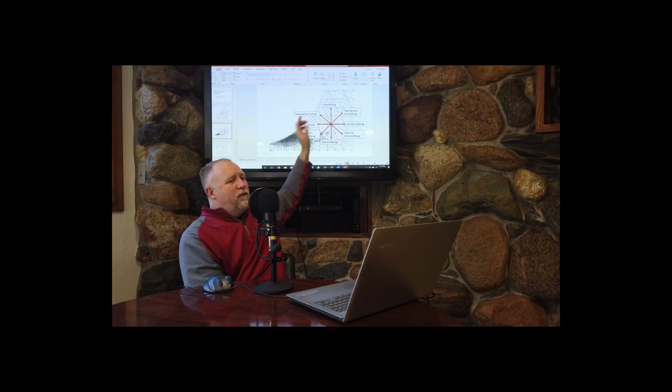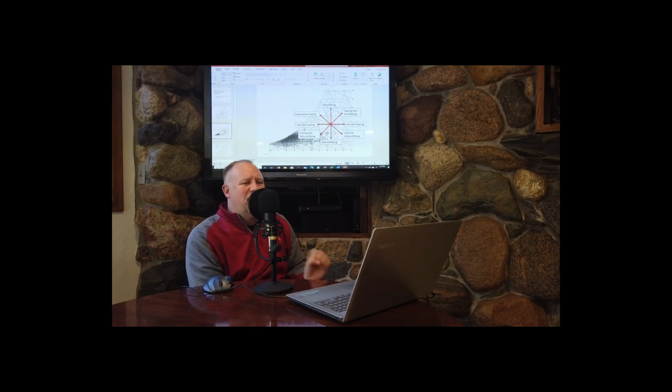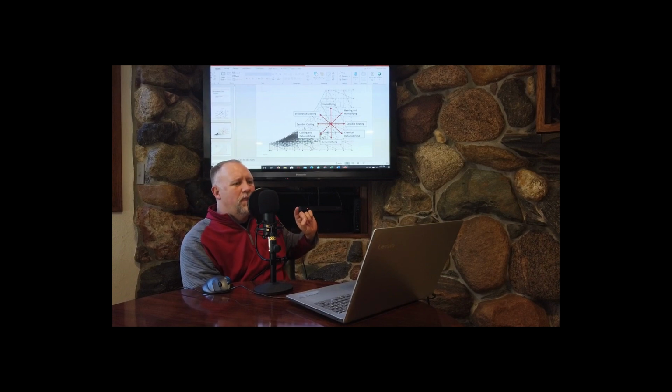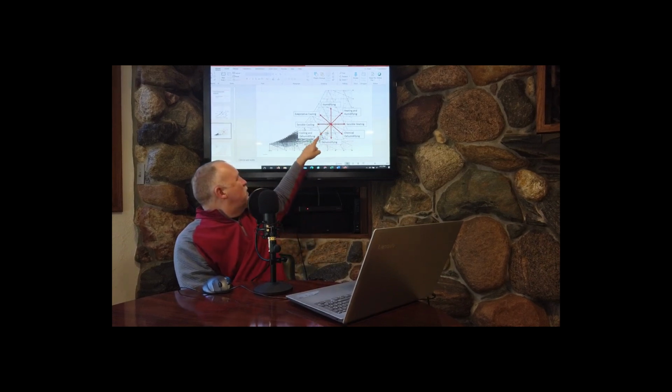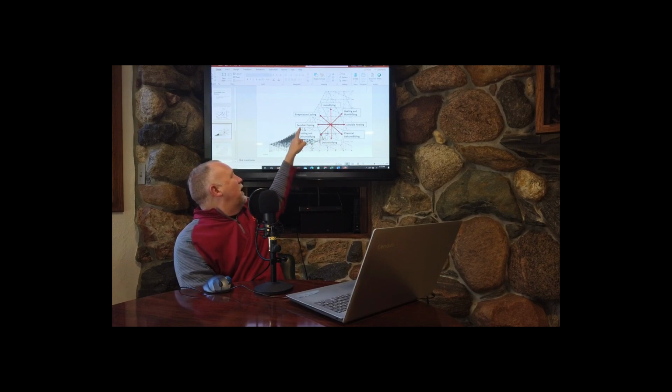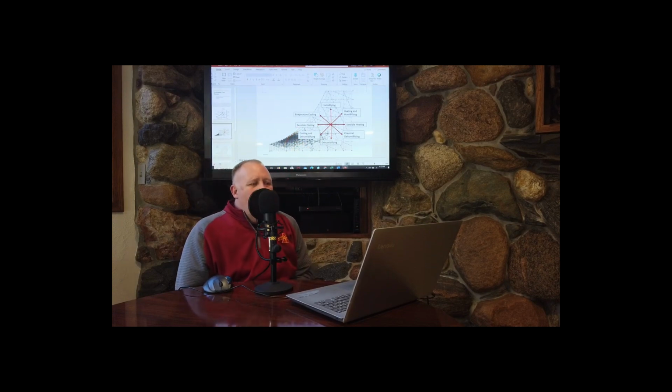Up and right, that's if we're heating and humidifying, like a steam humidifier. And then down and left, cooling and dehumidifying. However, something important to note is that you cannot do this directly, this line that goes down and to the left. First, you have to cool it down to the saturation line, and then you drop moisture. So this has to happen in two parts: first, sensible cooling, and then cooling and dehumidifying. All right, so that's how you're going to move around on this chart.